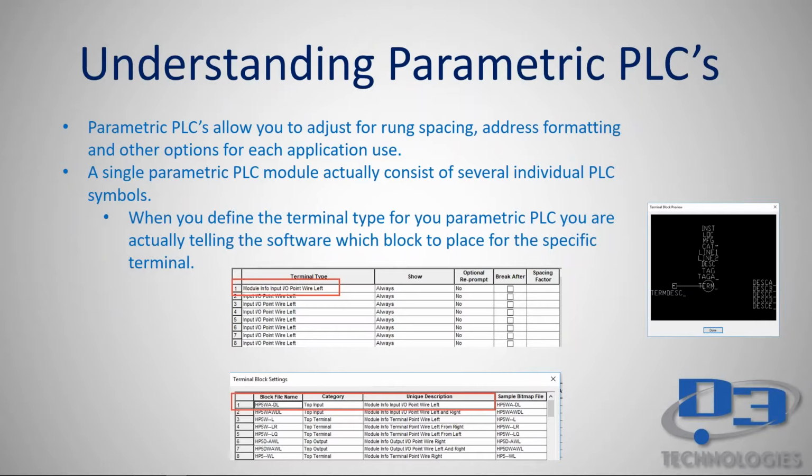We also have some flexibility as far as what options we're going to define for prompts, rack, slot, module number, etc., and defining the tagging format for your I/O points. So these are flexible PLC modules. They are database driven, so there is an Access database behind what we're looking at.